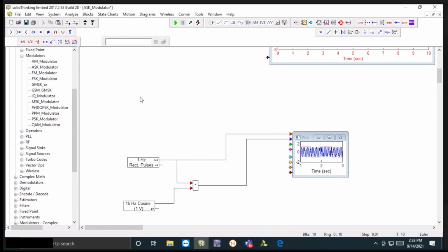Likewise, for the bipolar system, it will be omega plus delta for 1 and omega minus delta for -1. That means for the higher value, high frequency, and for the lower value, that is -1, lower frequency. So in the bipolar system, the only difference is that there will be a change in the frequency in both conditions. Either there will be an increase or a decrease in the carrier frequency.